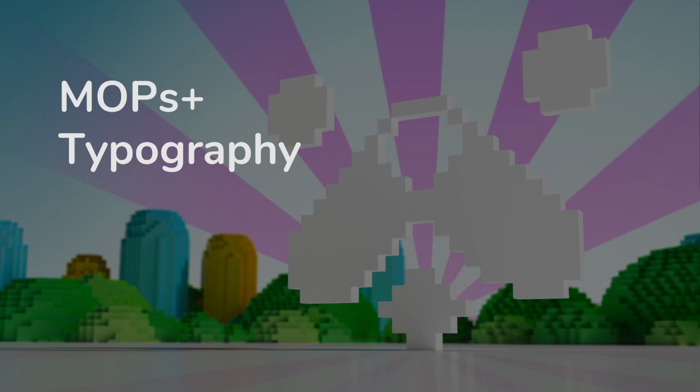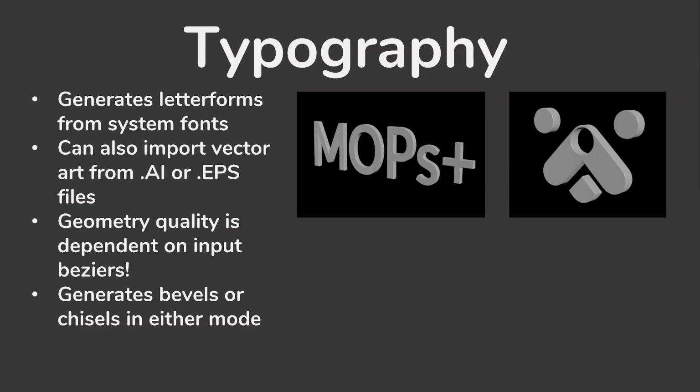Today's tutorial is about MOPs Typography. This is a very handy tool that generates letter forms in an intuitive manner with built-in controls for beveling, alignment, kerning, wrapping, and more. It outputs packed primitives that are ready to use with the rest of MOPs or with Houdini's native tools. MOPs Typography can either generate letter forms from fonts on disk, similar to the FontSOP, or it can read imported text and vector art from Adobe Illustrator or EPS files.